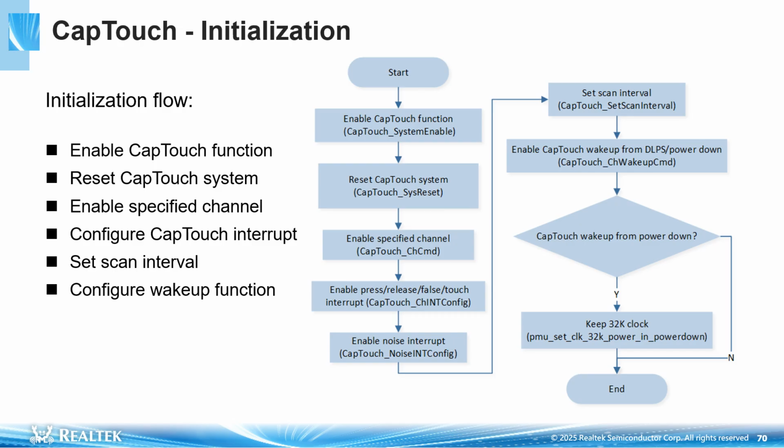The CapTouch initialization handling process is shown in the figure. First, enable the CapTouch function, reset the CapTouch system, then enable the specified channel, enable the CapTouch interrupt, set the scan interval, and finally set the wake-up function.